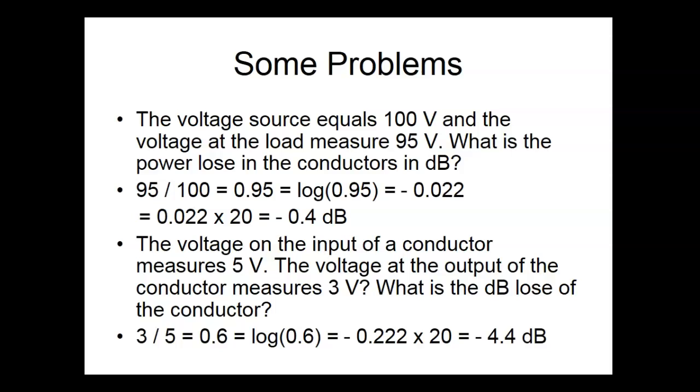And why do we need to know that? Because like I said, voltage is very easy to do what? It's very easy to measure. I can measure with an oscilloscope. I can measure with a meter. I can't measure current easily, right? Because to actually measure current, we have to break the circuit, right? I can't measure power directly. Power meters are not cheap. And you still have to break the circuit.